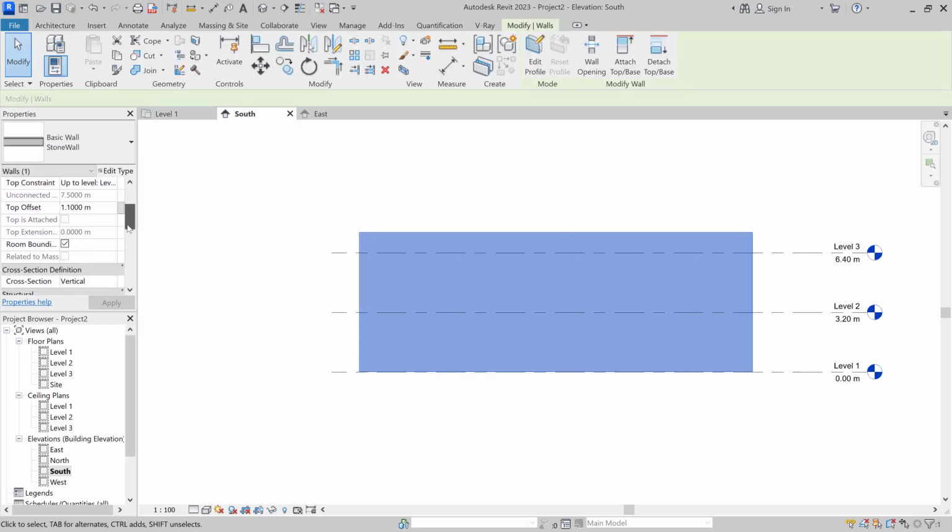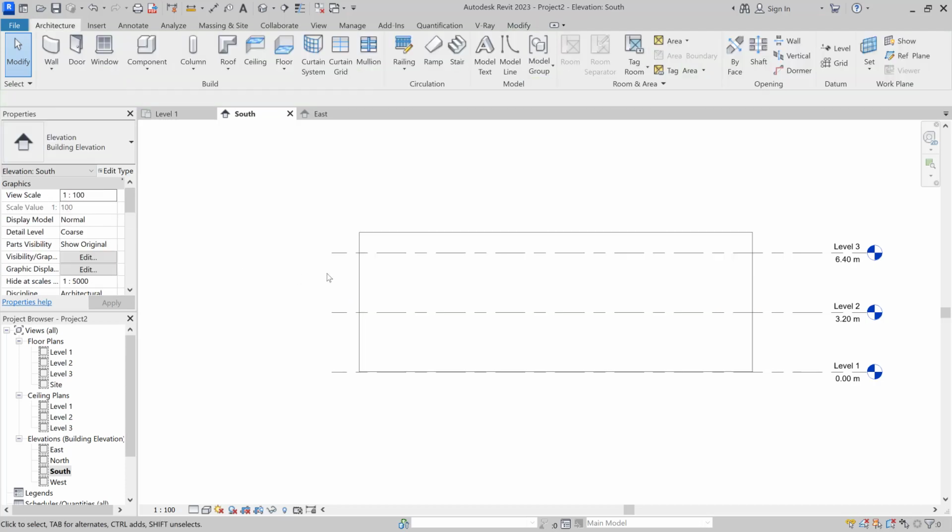There is not any other thing that we can go through for walls for now. You know the basics. You know how to create a wall. The next step is bringing a plan of yours, an image, a hand sketch, or whatever you want, to level 1 or level 2, and then just draw on it and create your levels and start drawing the walls. I will do the same. Once the walls are ready, we will go through the other parts of the project.